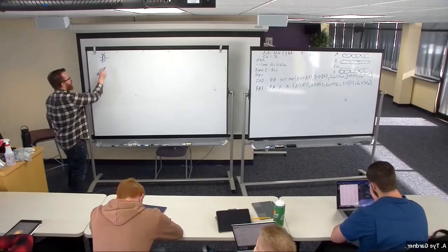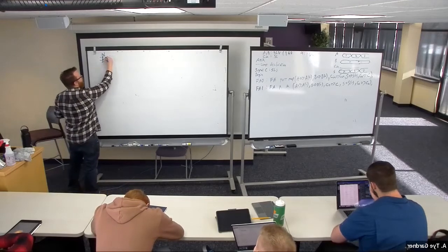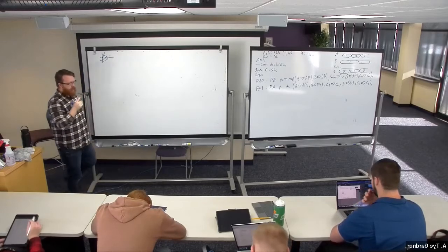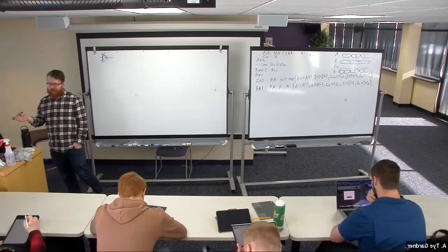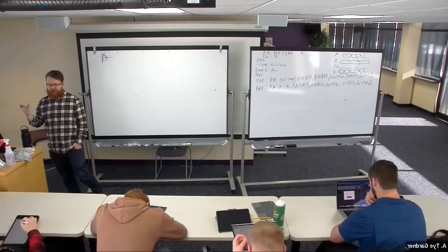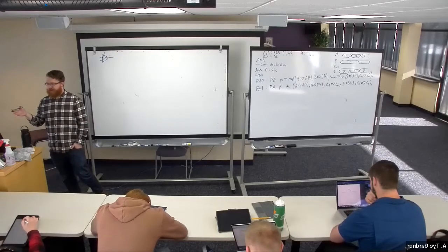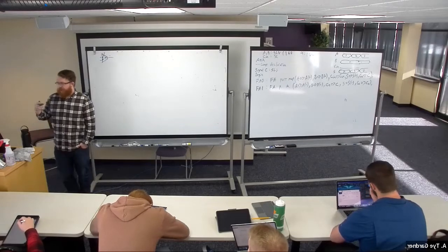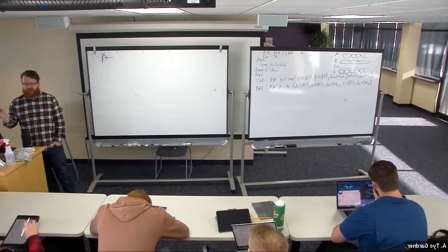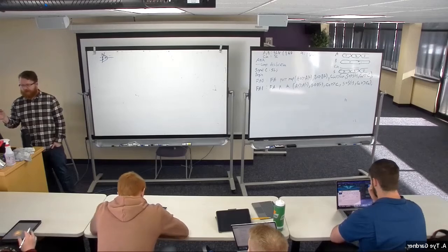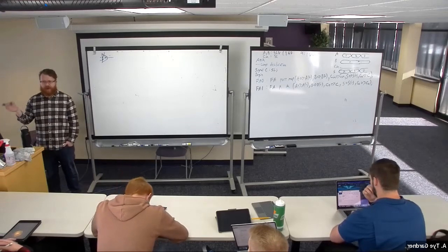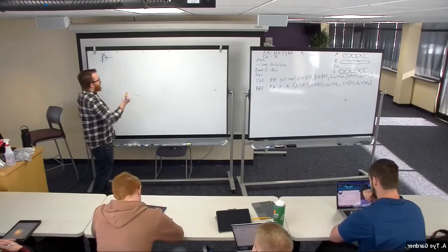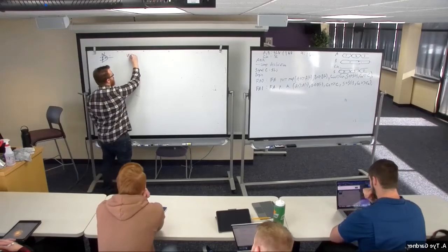So let's say I call this output M, as I've done before. I could either do a 3 input truth table with S, A, and B, or I can do what's called a select statement. Now I don't usually use the select statement that often. Instead, I usually use what are called when-else statements. But let's start with the with-select. If I do this one wrong, I'm sorry, because I almost never use this.